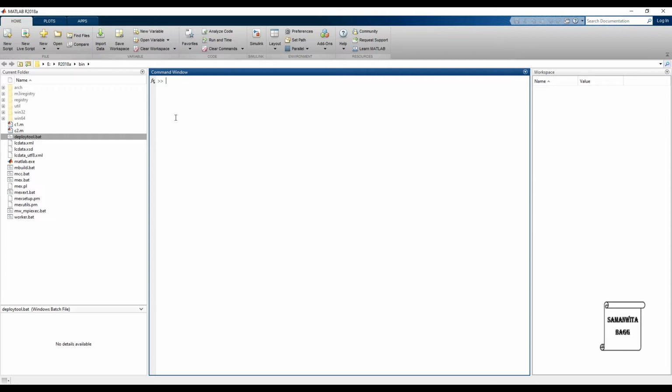Suppose I want to enter some array of data in MATLAB, it's very simple. Just write down the variable in which you want to store the entire array. Put a square bracket and write the numbers that you want to input as the array, say 1, 2, 3, 4, 5. These are the data that I want to input. Close the bracket. I have put space between the two numbers. You can just note that. I'll press enter. So these are the values of the variable a right now.